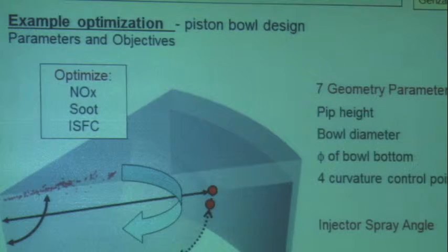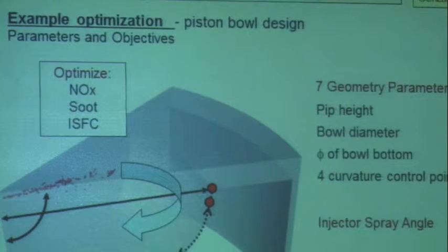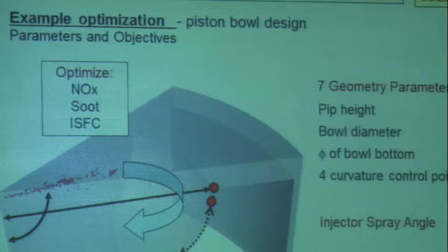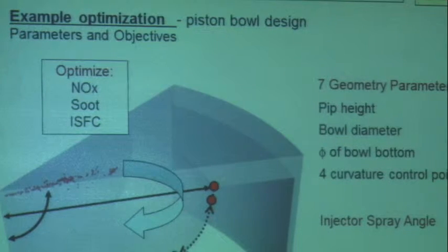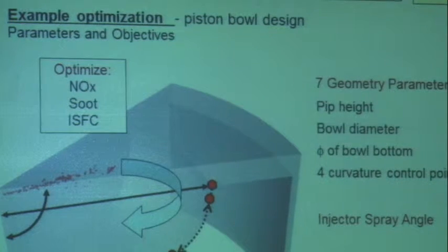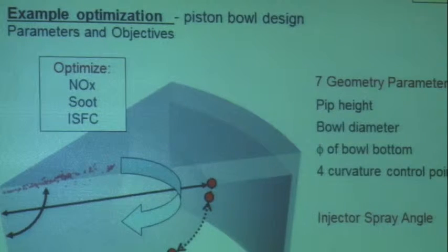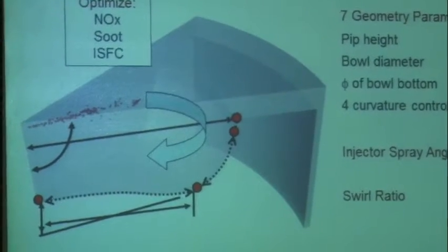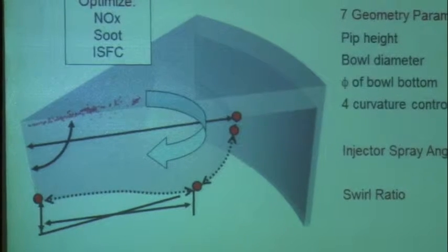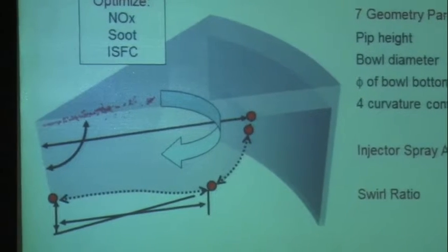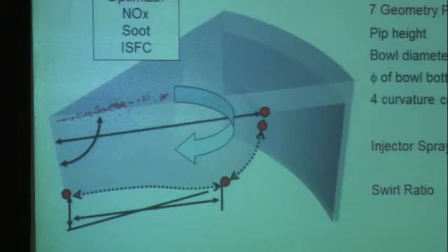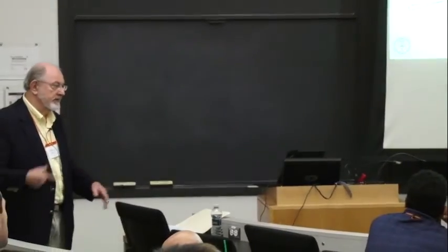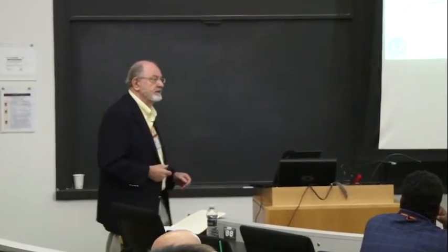Yeah, we've actually used both GAs and DOEs in the lab. And the students prefer the DOEs because you're kind of more in touch with the ranges, and you don't have this surprise where suddenly you're asked to run the engine at 50,000 RPM because that just happened to come out of the random selection. So the DOE is more controlled, but you can miss optima or the location of optimum points. Yeah.